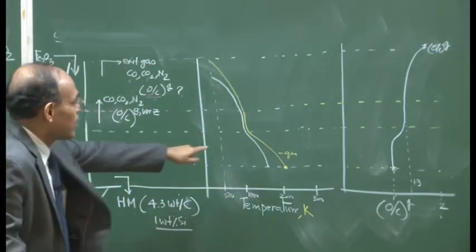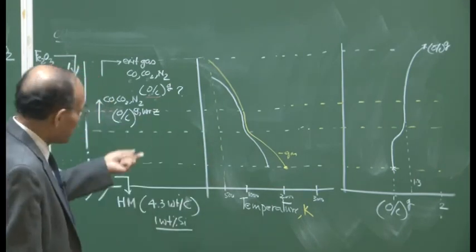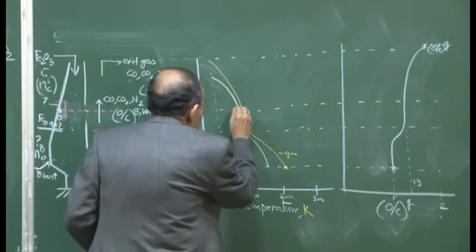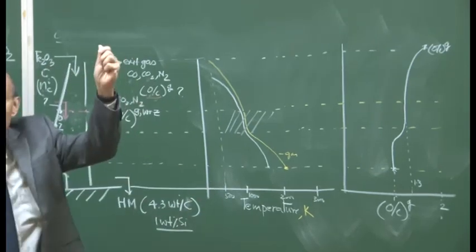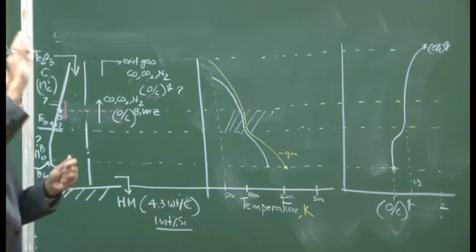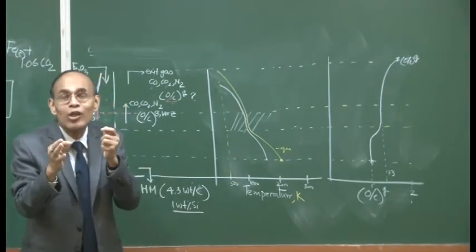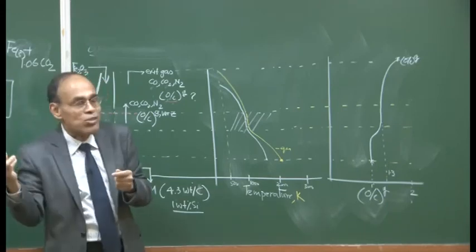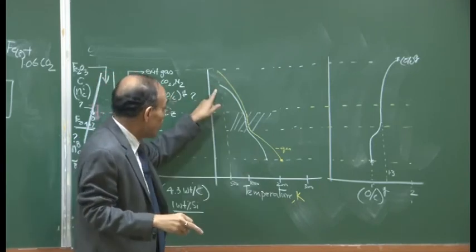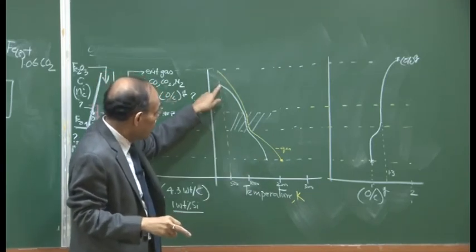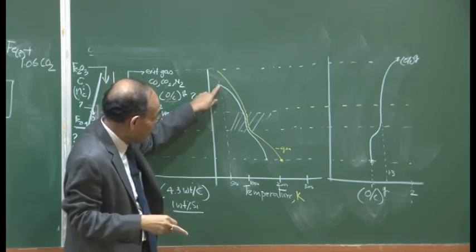As we look at the first graph, we can see that the gas and the liquid or the solid temperature varies, but there exists a region in the blast furnace. You can imagine that the gas and the solid are moving in opposite directions. So, there is a likelihood that in some region the gas and the solid will come to thermal equilibrium, because the gas from 2100 degrees will come down to 500 degrees, and the solid plus liquid, the other phases combined, will go from room temperature of 300 Kelvin to about 1500.